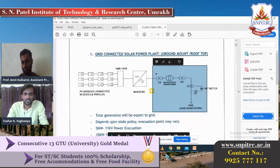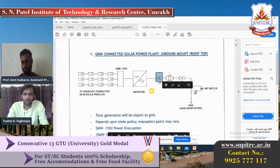There is some protection equipment. One is the circuit breaker, then the inverter duty transformer. Once again, circuit breaker, CT, PT, and ABT meter. So the inverter converts this power into AC. Then the circuit breaker comes into the picture for protection, and then the inverter duty transformer. The function of the inverter duty transformer is to match the voltage and frequency between the grid and the inverter.